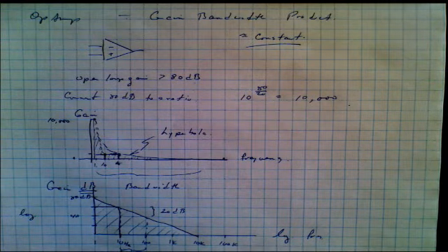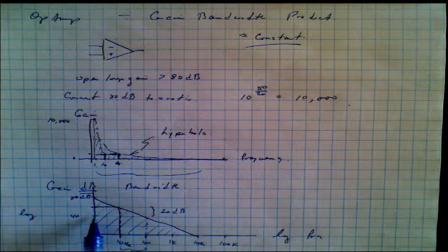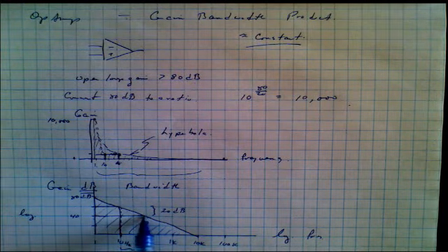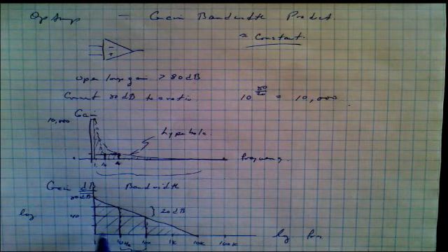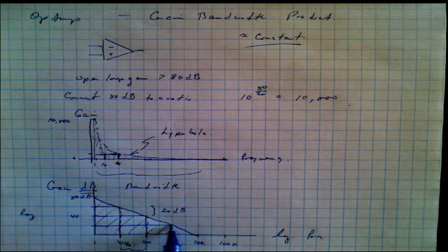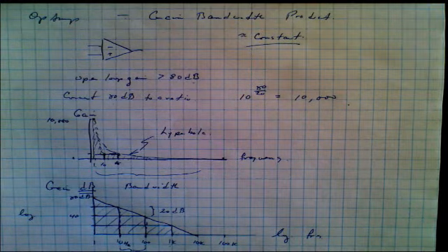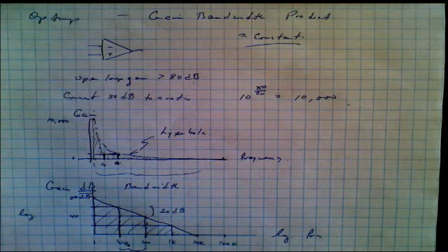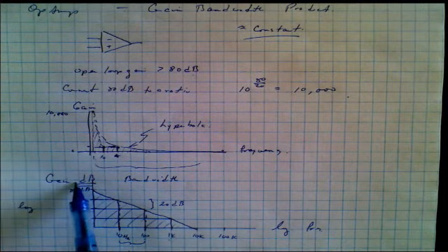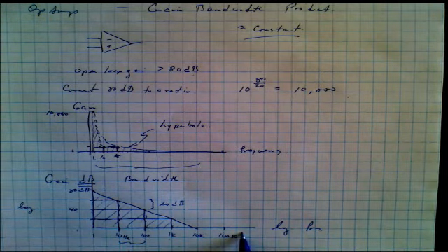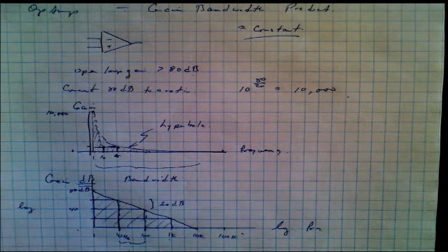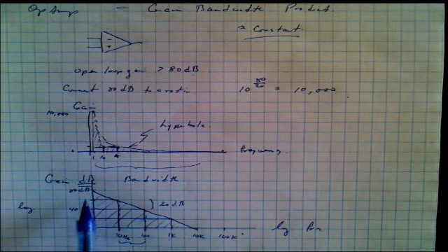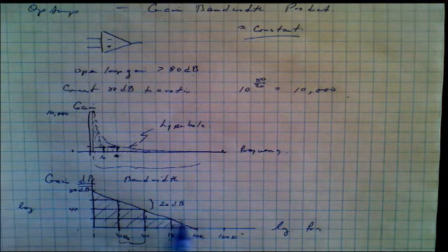So that's really, really a subwoofer. If I said I wanted a circuit of 40 dB, I could get a bandwidth of 100 hertz. If I wanted 20 dB, I could get a circuit that enters the audio range at 1 kilohertz. So notice what happens with circuit design: you trade off gain for bandwidth. This means that operational amplifiers are designed to have exceptionally high open loop gains, very, very high gains. And the reason for that is so that you can lower that gain and get a much wider usable band of frequencies.